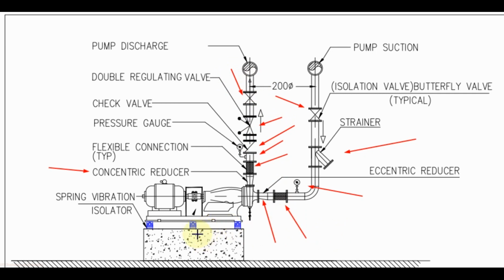For the base of the pump, if you are using the pump on a higher floor, then you should use an inertia base here. Otherwise you can use a normal concrete pad with the vibration isolator.